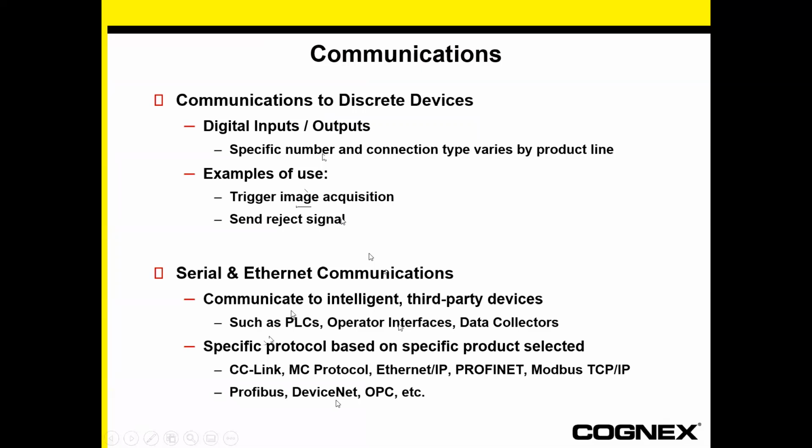Alternatively, we have serial and Ethernet communications. So there are different protocols to talk to PLCs, operator interfaces, data collectors. We've got a lot of the most common ones, Ethernet IP, Profinet, Modbus TCP IP, MC protocol, CC link for your Mitsubishi products.